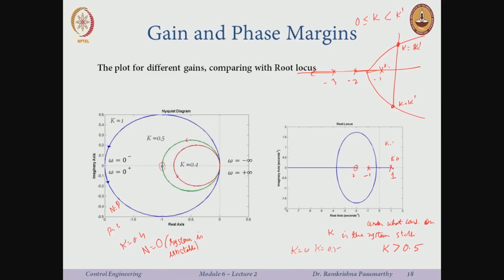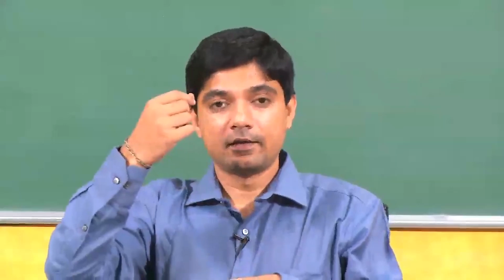correct. So, I start with an open loop unstable system, and the system is unstable until I have a certain gain. Therefore, we call these systems a system with a negative gain margin, right. So, the earlier problems were formulated in such a way that how much can I increase the gain k before it becomes unstable, okay.